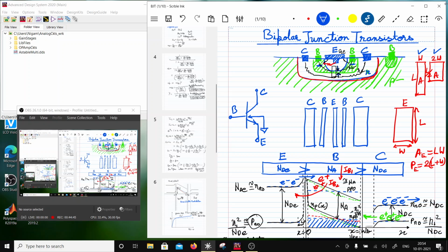So if you think that you can make much smaller bipolar transistors by cutting short the length and increasing the width, you are terribly wrong. This has caused a big business to fail when we were doing silicon germanium. This was the main reason for seven products to fail when we tried to reduce the die size by reducing the length and doubling the width.